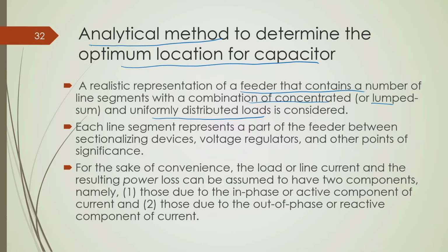Also, in the different line segments of the feeder, we have sectionalizing switches and many other compensation devices. For the sake of convenience, we assume that the power loss can be represented with the in phase component of the current and the quadrature or out of phase component of the current, which I already mentioned in my first lecture of this module.